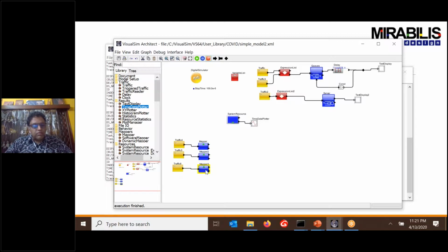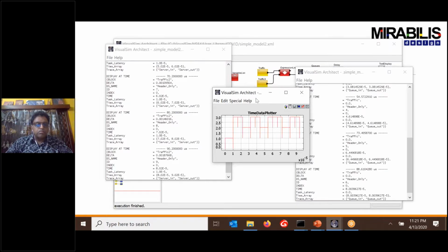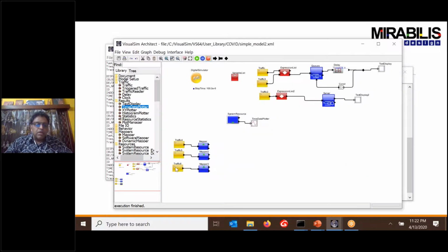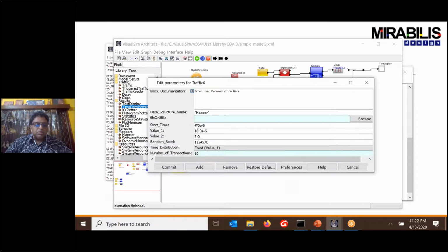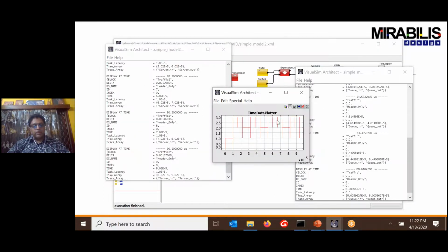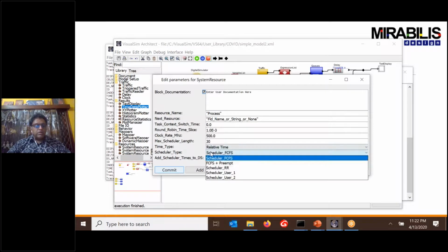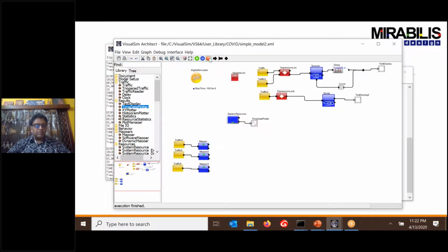Now for this one here, I'm going to reduce the processing time to say 6. Now what you see is, this one comes in, the next one comes along immediately, then the second task completes, then 2 of these, now 3 of these. It's a variable number, because this starts off at 4 and goes to 10, so there's a possibility of some of them jumping in between. We saw this plot over here. Now we're going to introduce preemption to the exact same design.